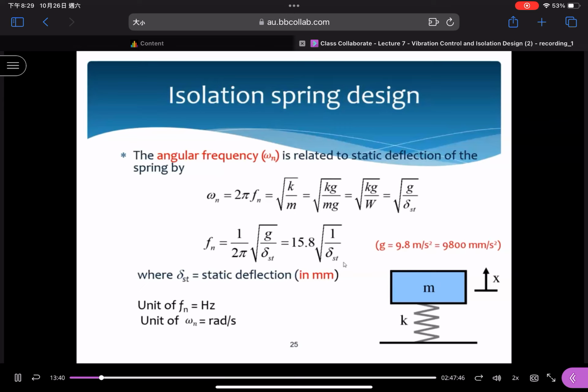And how about S naught here? S naught is the displacement at time equal to 0. V naught and S naught, both conditions should be given, otherwise you cannot find the value. So when we refer to this, V naught is the initial velocity, and zeta is the damping ratio. Omega n is the natural frequency. S naught is the displacement at time equal to 0.